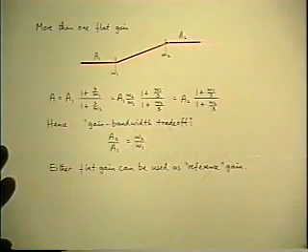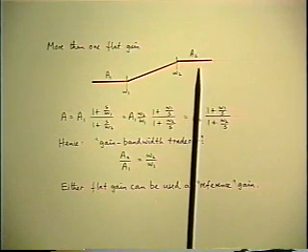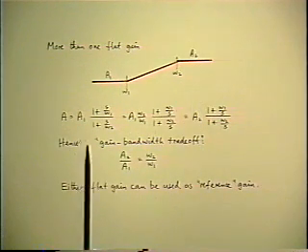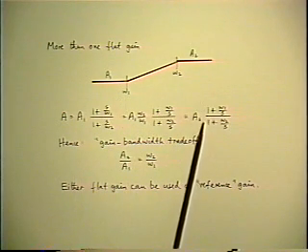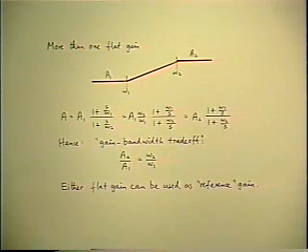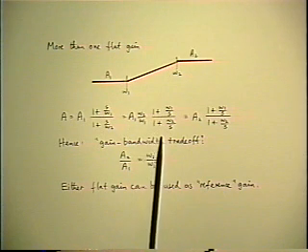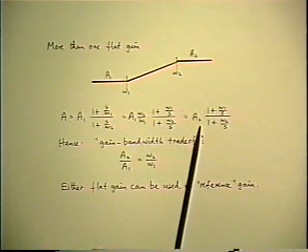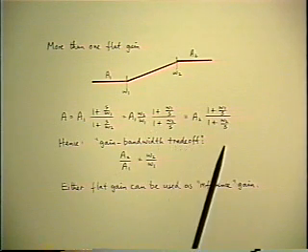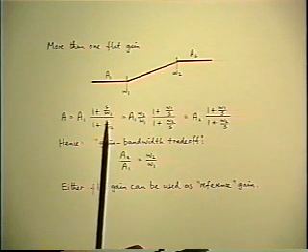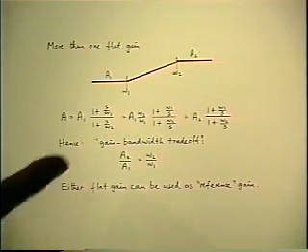Okay, so the conclusion of that particular topic is, if you have more than one flat gain, you have a choice of which one to set out front as the reference. And you notice a trend here, because obviously you can extend this to any number of flat gains. Whatever flat gain you choose as a reference, corner frequencies that are above that gain will show up in normal format. Corner frequencies that are below it will show up in inverted format.